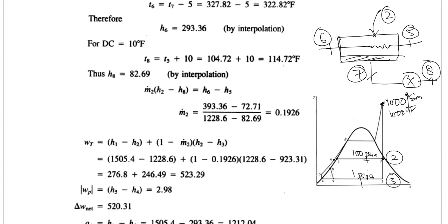In that case, the temperature exiting at 7 should be equal to the temperature at state 6. So that means these terminal temperatures should be equal if it is 100% energy transfer. But as you can imagine, there might be some tubing installed, there might be other factors which would reduce the efficiency.